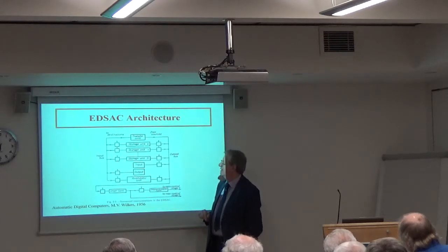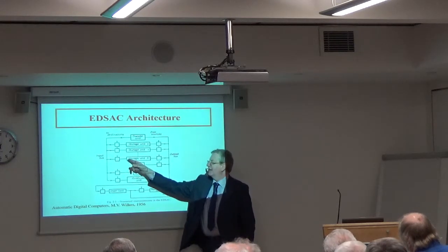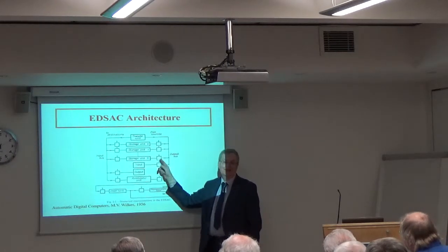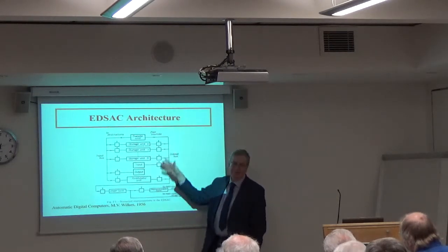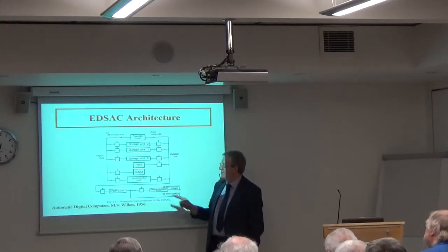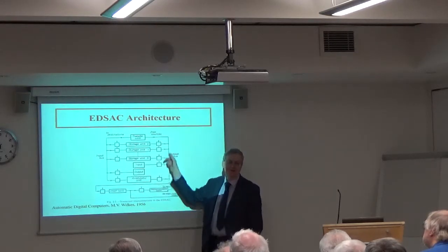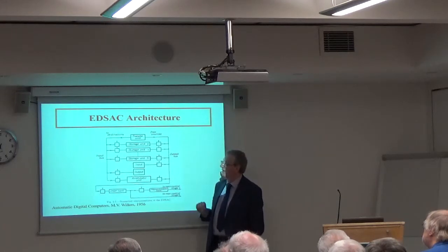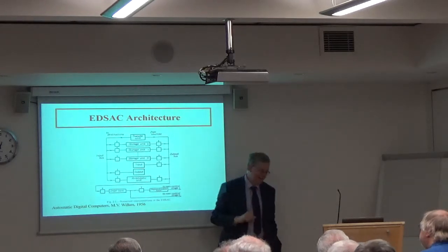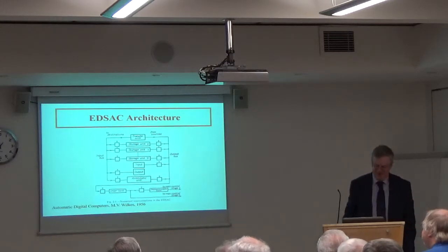You can only take data into the store at the right moment when the word you're addressing is about to go into the delay line, and you can only take data out of the store when that data is coming out of the delay line. So there's quite a lot of quite tolerant synchronization in there. And in terms of debugging the machine as you're building it, it's quite a challenge because you've got layers of wheels within wheels within wheels. And sometimes to get round to seeing the same signal reasserting itself, you've got to wait quite a long time for everything else to happen, and that can make debugging challenging. We have to build ourselves some interesting debugging aids.